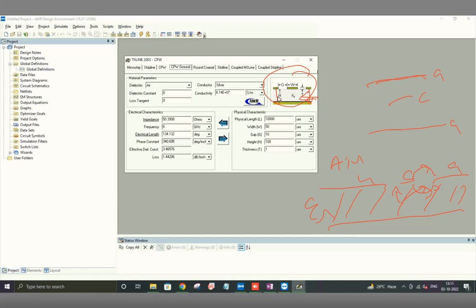So if you think about it, it now actually looks like half a coax. Right? There is a ground here, there is a ground here, and I've actually connected this ground to this ground. Maybe it's like a rectangular coax. So that's what a CPWG is really like. It's like a little bucket of ground plane and then there's a center pin in the middle. But this has to be done, and that requires vias, they're called via holes. So that's CPWG, but I'm just quickly going through this.